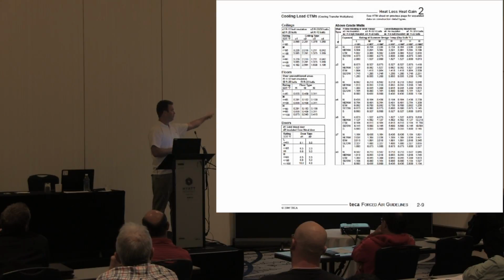So the other balance point temperature one for guys that are doing this kind of system is to get them to try to do the math calculation for the economic balance point, because what you may find is that the numbers aren't exactly the same. It might actually be a few degrees warmer, where it's better for you to turn to the gas earlier than what this calculation tells you to turn it over for.